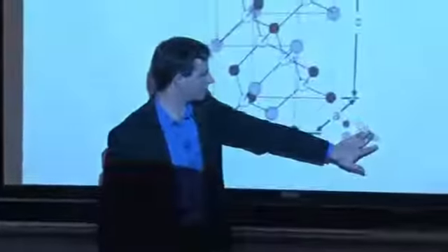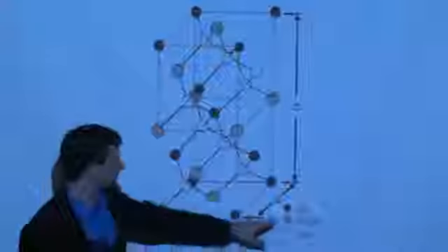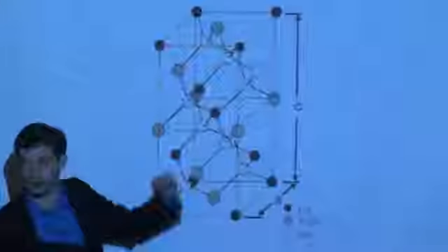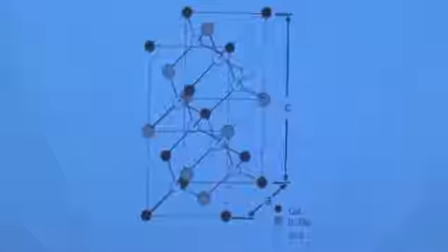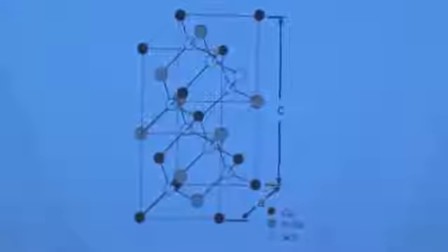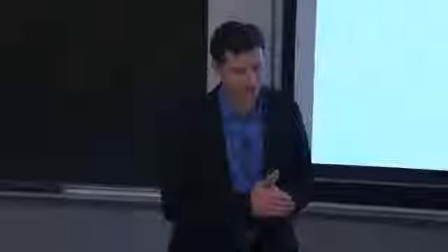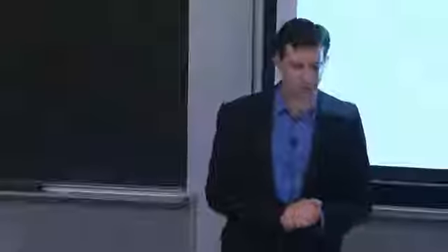So copper being on the far right-hand side of the 3D elemental series has a smaller atomic radius compared to, say, iron or manganese or titanium. And as a result, it could move fairly easily throughout the lattice if it is present in a charged state, if you have, say, copper plus, and a large electric field distributed across a thin film solar cell device. So copper sulfide devices ended up degrading quickly over time, and it was realized that some heavier elements needed to be included to stabilize the crystal structure.